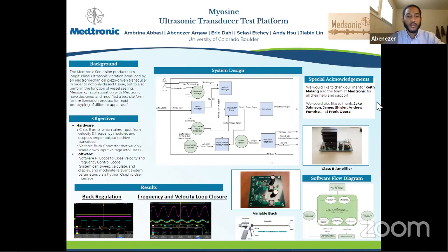Another trouble we went through was accidentally flashing our board with code that didn't allow us to reprogram our board again. This was because we had initially switched it to our synthesizer clock, which is our external clock, at the beginning of our operation. And whenever that happens, there was just some communication error with our debugger and our board. And for a little bit, we had a board that was bricked, and we had to hard reset our flash to get rid of that memory or that code.